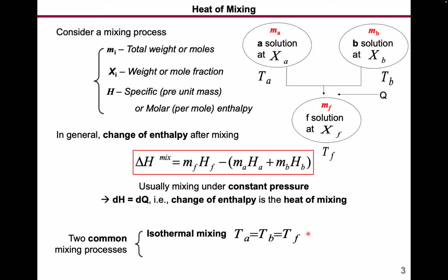So if it's an exothermic mixing process, you generate heat, and the system may rise in temperature, but you need to add some cooling medium to absorb the heat that is generated and maintain the temperature constant. That's a pretty common practice in chemical engineering processes and also in lab operations when you operate a mixing process. Okay, so like I said, for exothermic, your Q is going to be negative, and for endothermic, your Q is going to be greater than 0, or positive.